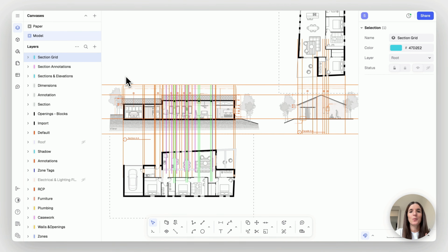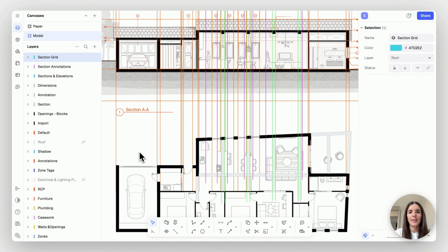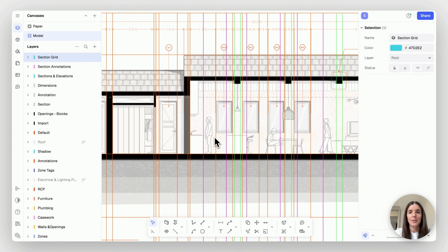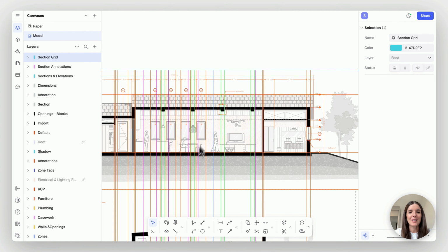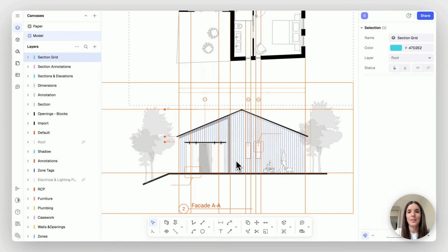As I insinuated when we copied and rotated these different views, the same as I did for the section. So place the floor plan in the direction that I want to cut it, add my grid lines. So you can see here I have different colors. The green lines are for the beams holding up the ceiling. The pink magenta ones are for the placement of the furniture on the floor plan. This just helps me within all these lines to build my grid. And the same approach applies to facades as well.